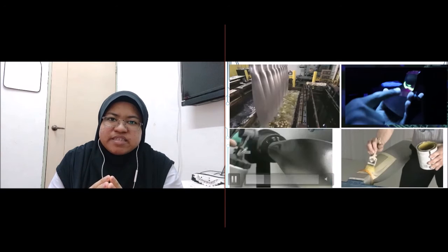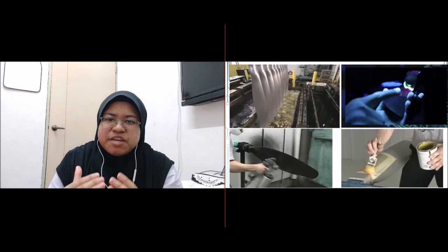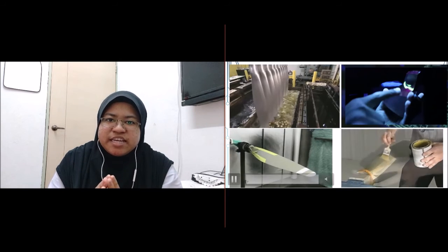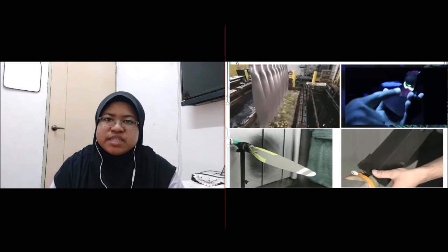For safety reasons, stripes are added at the blade tip to make the spinning blade visible. Next, the de-icing boot is installed on the propeller's leading edge. Then, we come to the assembly process. A part of the blade shank is lubricated with grease. A strong steel ball bearing system is installed. The shanks of the blade are installed by using a steel pipe called the fork.